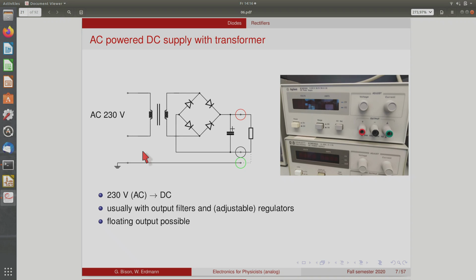No, except that sometimes there is a device that limits the voltage between the black and the green. That could, for instance, be one of these diodes that we'll come to next time, I think, the Zener diodes. They limit the voltage between 2 points. So sometimes to make things safe, you don't want to have 10,000 volt between the two, because whatever you connected on the other side gives you a voltage of 10,000 volts. You don't want that to feed into your device that would either destroy it or endanger you.